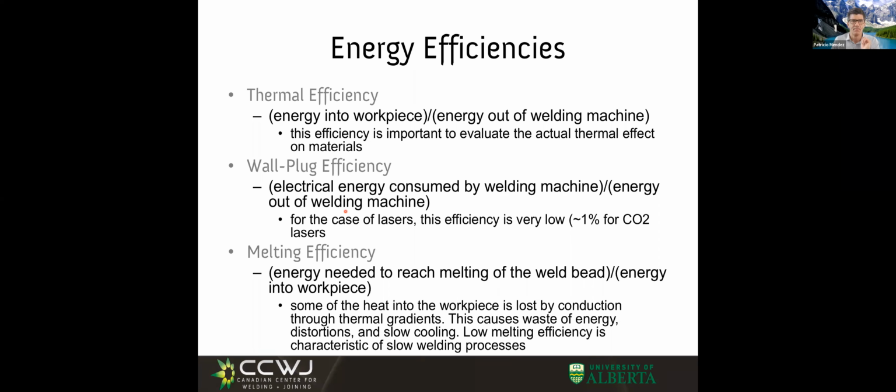There's another efficiency that is called the wall plug efficiency. That is how much energy... so this wall plug efficiency, the way I wrote it is backward. It's one over the other. No, I flip it. It is how much energy comes out of the welding machine divided by how much energy I took from the electrical supply, right? For example, in the case of lasers, that's super low. We discussed that when we discussed laser.